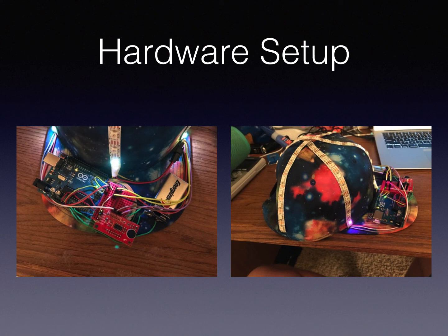On the left picture there, on the left is the Arduino Uno that you can see. I'm only using 2 of the analog pins, one for the envelope input from the microphone, and then one that is writing out to all of the LED strips.